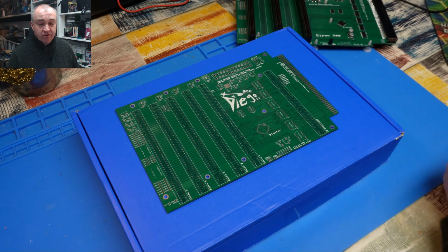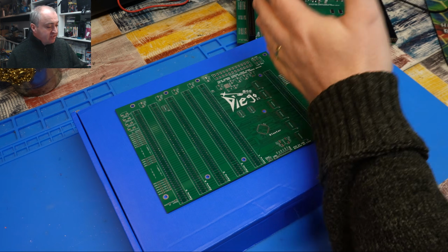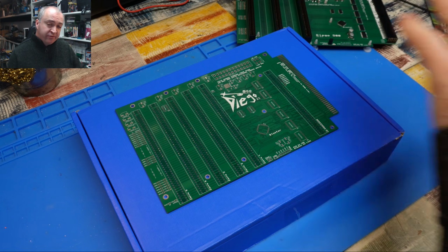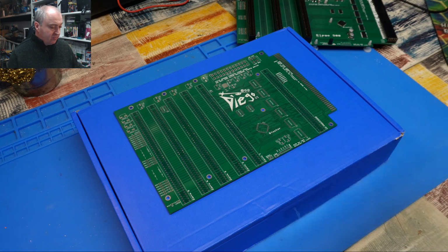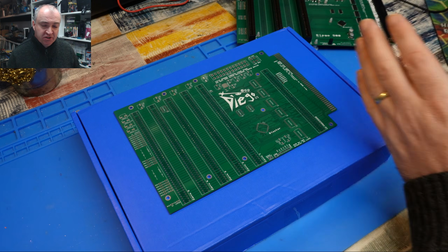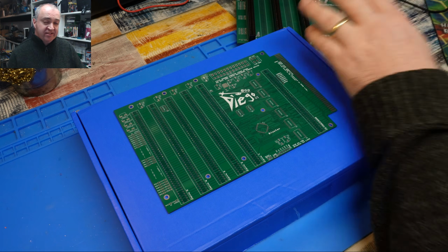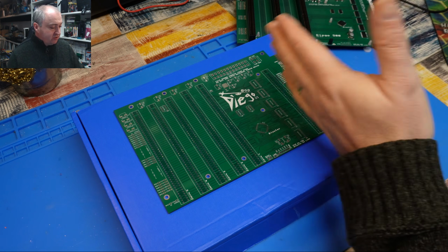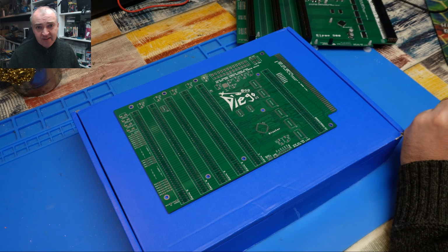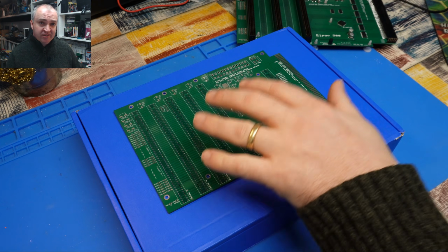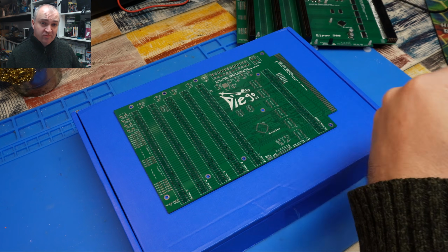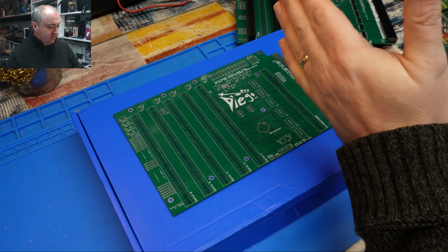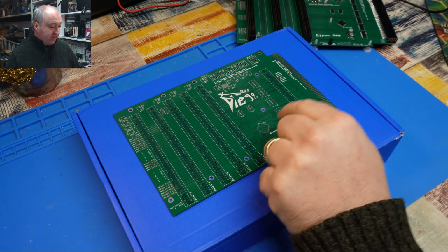So if you put your, I don't know, A2630 accelerator card into that coprocessor slot, it will do the negotiation through Bluster, just like we explained, but then it will assert bus. And that's so it can tri-state the CPU inside the Amiga, basically disconnecting it from the bus permanently so that the CPU card can take over. But the rest of the bus mastering can still continue to happen, just like it always would, although this time it's only between the ZORRO slots and the coprocessor slot via Bluster.